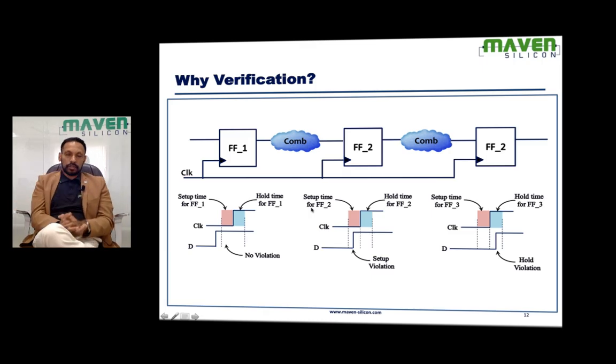There are two ways. You can run timing simulation and check whether there are any timing violations, but that's going to be very slow because you are going to run simulation on the netlist. The RTL itself is a structural unit which is slow during simulation, but you have converted RTL into a netlist further. Now the entire RTL is in terms of gates. So that's going to be still very slow. So nobody prefers simulation for timing verification.